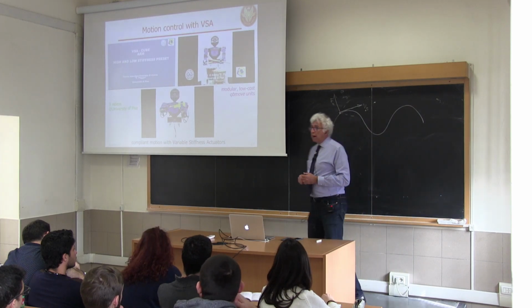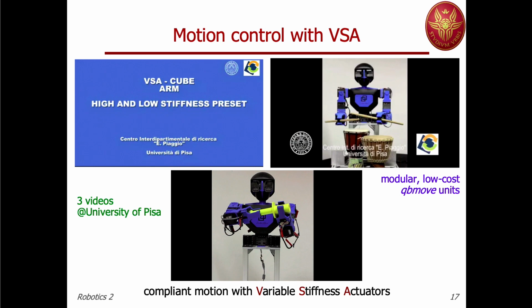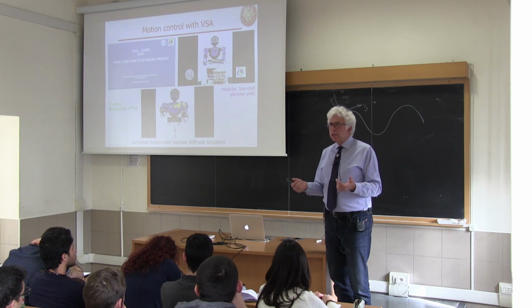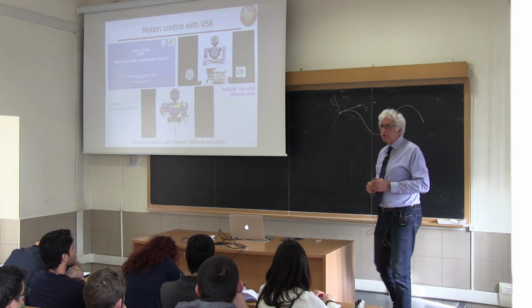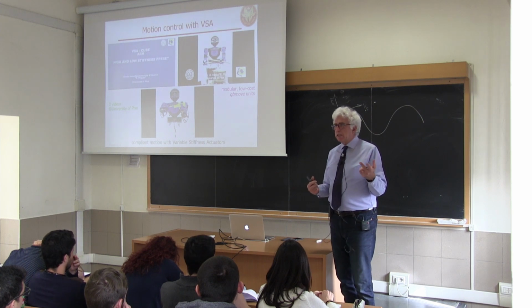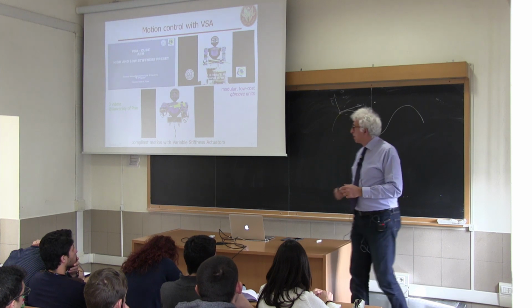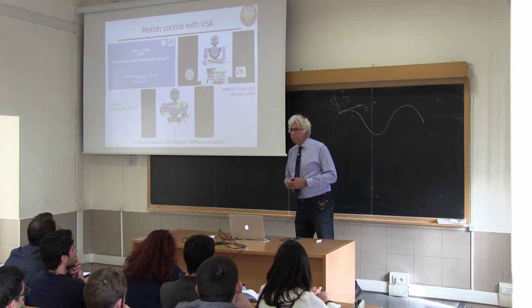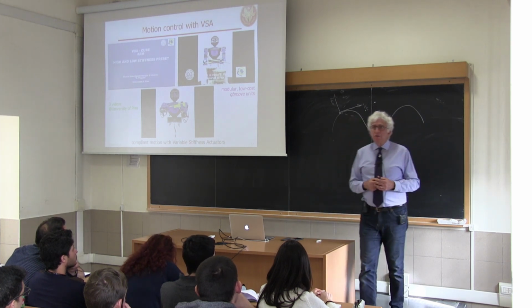Okay, so these are examples of joint compliance that contribute to the motion and which should be controlled. There are other situations, as I said, where you on purpose introduce a very large compliance at the joints, under the condition that you're able to modify it online without opening the structure. So you have extra motors that can be commanded in such a way that you perform this type of modification of the joint stiffness. As I mentioned last time, it's like in our body having two agonistic-antagonistic muscles acting on one joint, like our biceps and triceps.